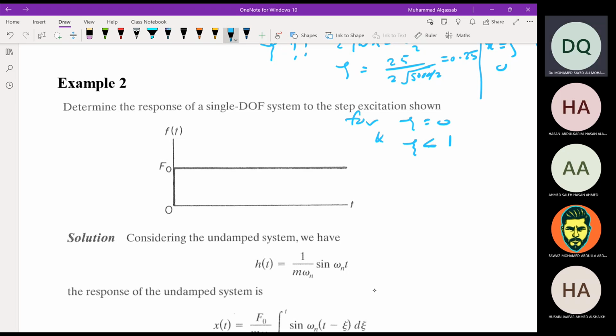So if the car comes, let's say that the wheels are rigid, with a step, the wheel is going to have a step suddenly, there is no rise here. Suddenly it will jump. So this will give an excitation to the system with sudden changes in the velocity, and you can have severe vibration, depending on the value of the step.